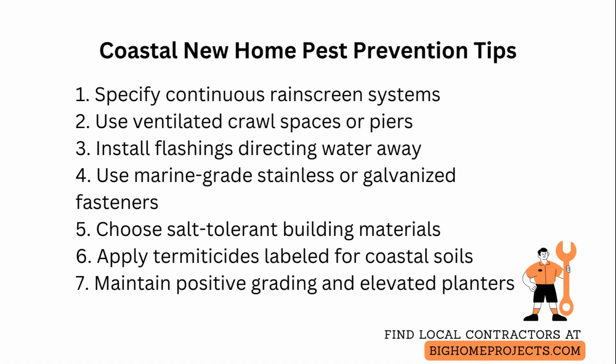Schedule inspection protocols that increase frequency after storms, seasonal high humidity, and during the first 5 years post-construction when settlement and minor defects commonly appear, and document findings in a maintenance log for owners and contractors.